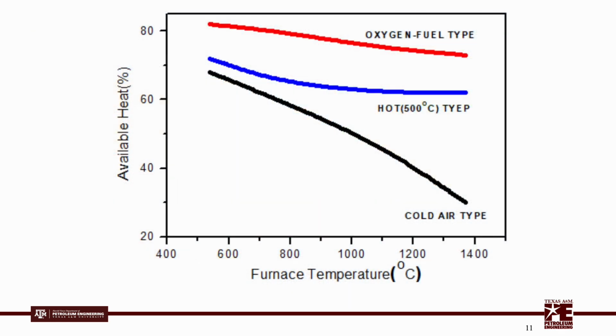By using oxygen as the oxidizing agent, the combustion efficiency is more than doubled as compared with the conventional air combustion system because nitrogen, which is a substance which hinders the combustion as it absorbs the heat without heat transfer, is removed.